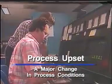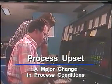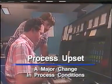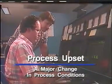A common term for a process problem that may affect one or more process variables is process upset. An upset is generally defined as any major change in process conditions that could result in unsafe operating conditions, or that produces a product that is off specifications, or both. The following are examples of process upsets. As we go through them, try and determine which ones cannot be returned to set point by automatic controls.